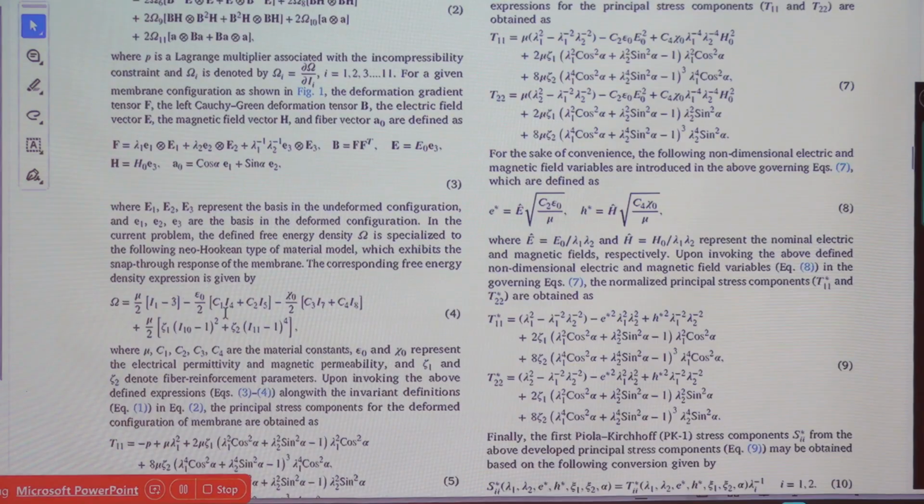So this is the strain energy. Where does it come from? The augmented energy, in which we initialize with the Neo-Hookean model. This term is for the mechanical part, the Neo-Hookean part. This is the electric part, this is the magnetic part. Epsilon naught is the electric permittivity and mu naught is the magnetic permeability. Then we have the transversely isotropic part, mu by 2 Xi into the particular direction where you are incorporating the fiber. That term squared will come, but an additional higher order term will also come here, because we are considering 2 Xi1 here.